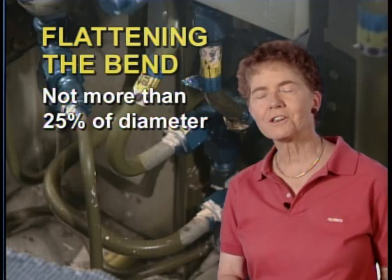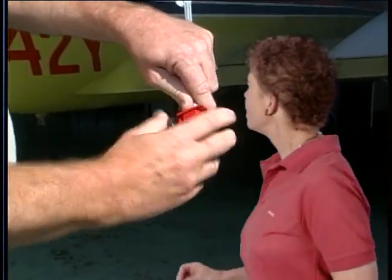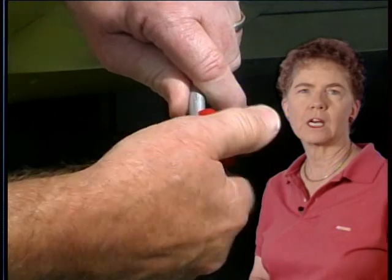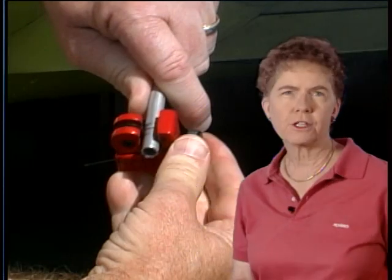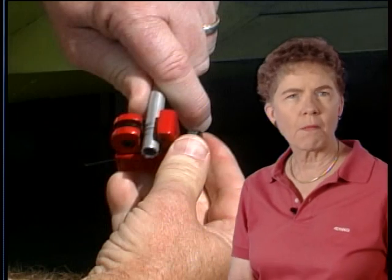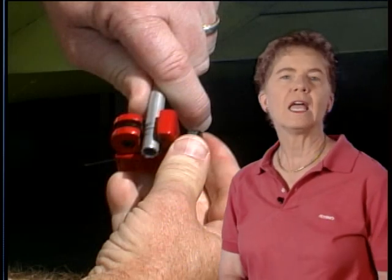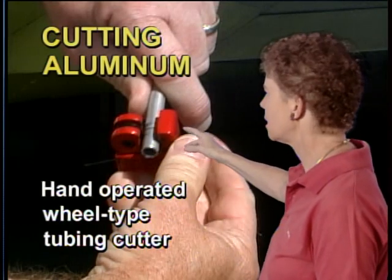Now, in addition to bending tubing, you'll most likely have to cut it. When you're cutting a metal tube, it's important to make sure that it ends up with a square end. And the best tool for cutting moderately soft metal tubing, such as that made of aluminum, is a hand-operated wheel-type tubing cutter.